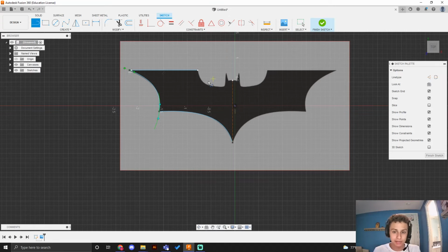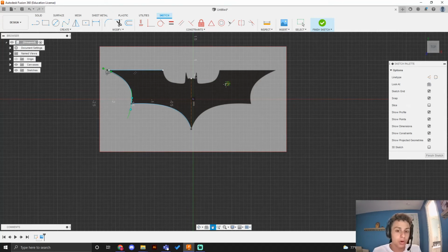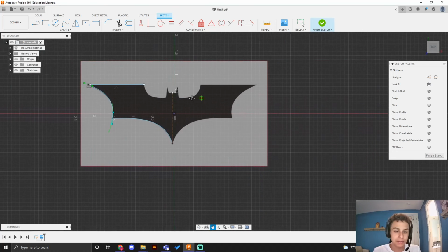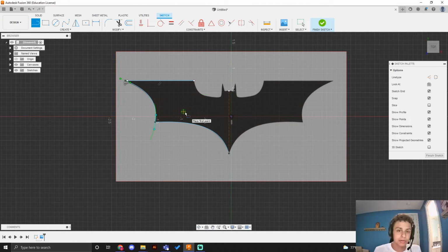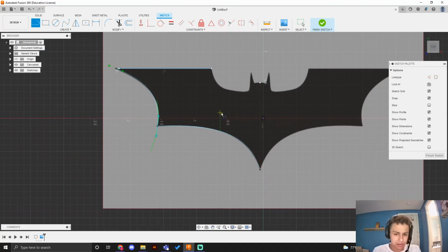And I showed you guys how to zoom in and out. It's just a scroll wheel. You may be wondering how I'm panning left and right, and I'll show you real quick. You press down on the middle mouse button, like hold it down like this, and you can see at the bottom the pan tool right here is being selected. So I press down the middle mouse button and I move my screen left, right, up, down, and that's how you pan.